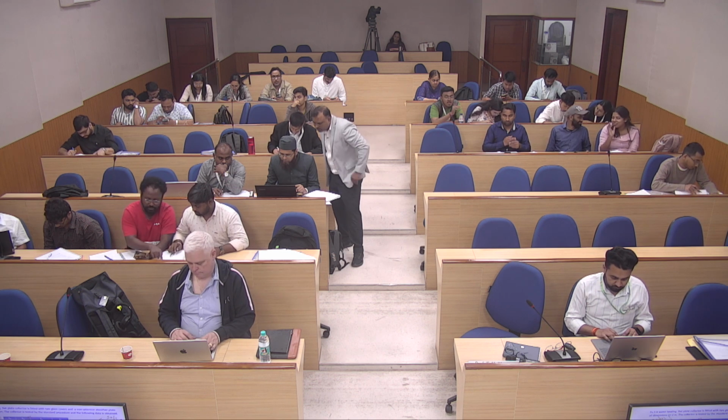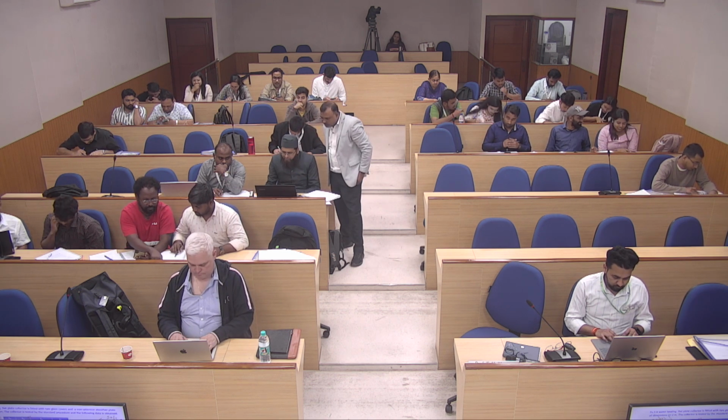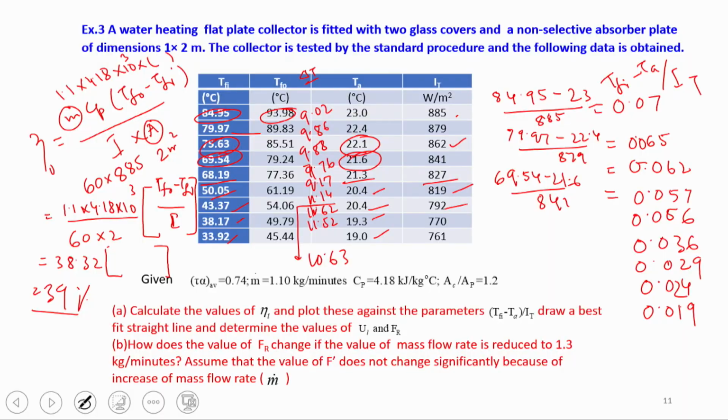No, third line. And after that here, Linear, and more options we click, and Linear equations. So the equation will be there. Display equations also, and R-squared values. So let's make it big.